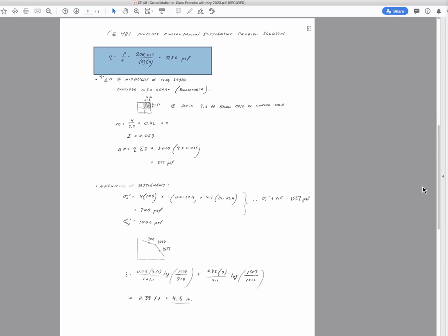And we will evaluate delta sigma at the mid-height of the clay layer. I had some groups considering where should that be. It is most common to do it at the mid-height of a layer because that would be representative. And if you want to get more precise than this, more representative than this, you would subdivide it into different layers and then work at the mid-height of each of those sublayers.